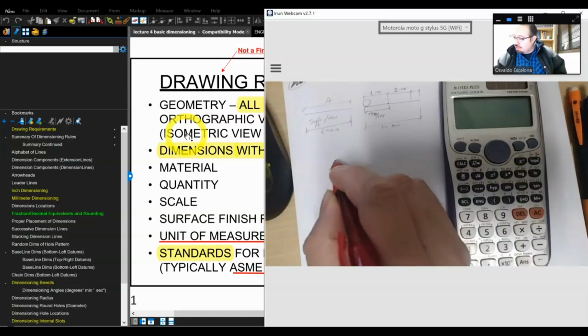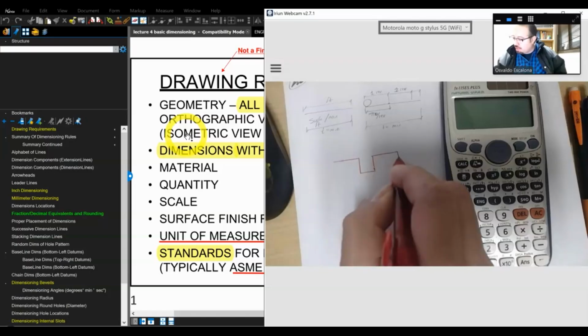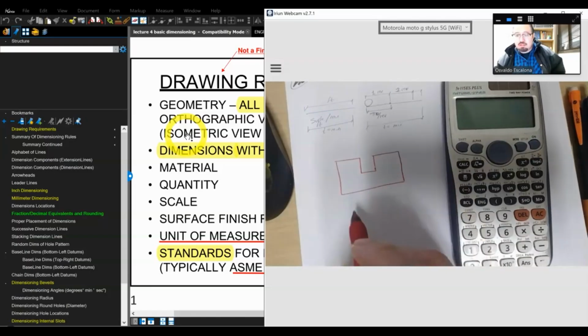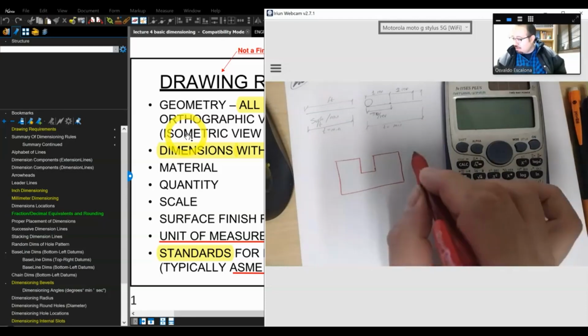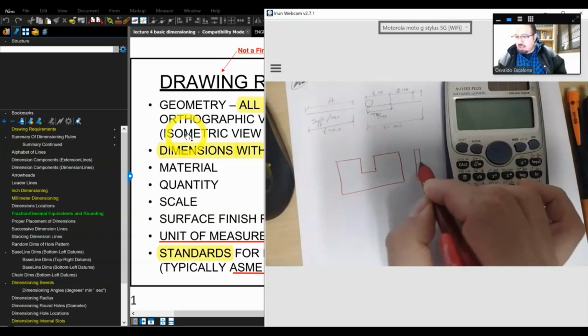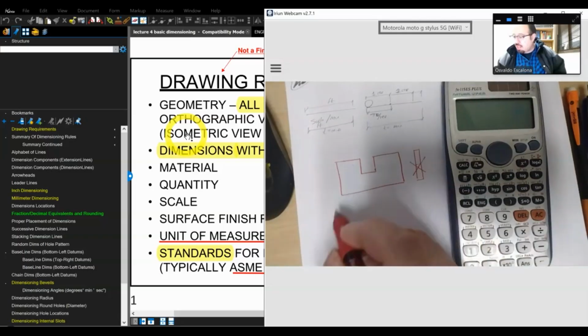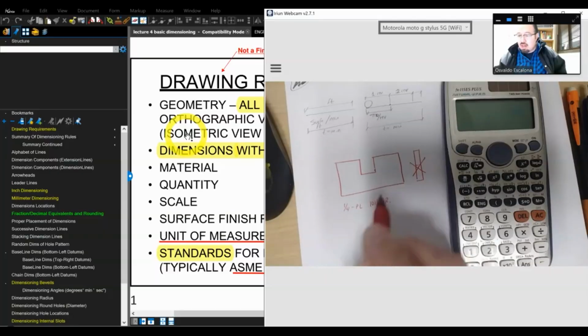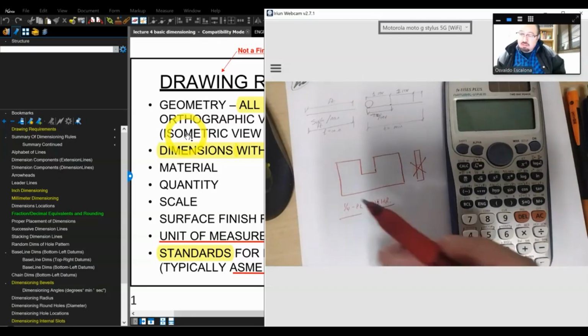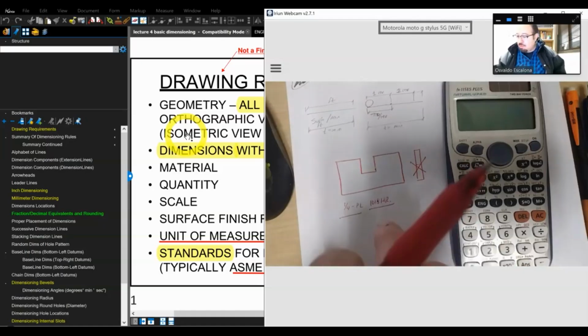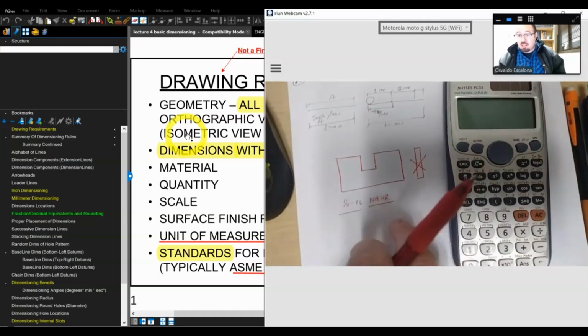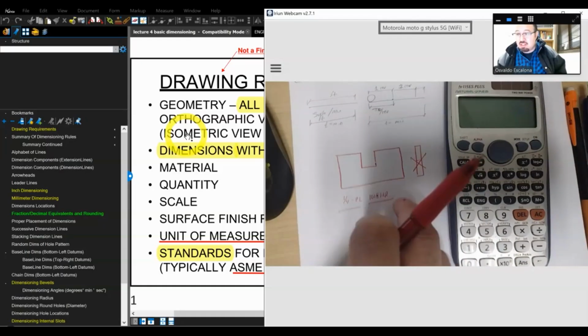Let's suppose that I have a piece of sheet metal that looks like this. Alright? It's just a piece of sheet metal. It has a feature like this. Do I need a side view? Do I need to come over here and put a little line and highlight? I don't think I need it. Why? Because I can call out the thickness of the material. I can say a 1/4 inch plate, 1018 hot rolled steel. I know the material and I know the thickness. Boom, done. Right? Do I need a top view? No. So you will create the views that are necessary to be able to convey your design intent.